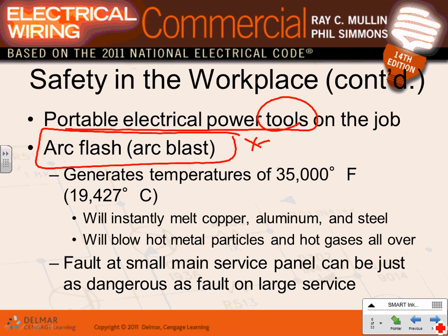If you are within 5 feet, your chances of having a first, second, or third degree burn are very high. Number two, your chance of being pushed against the other wall as a projectile is also very high, and your chances of losing your hearing because it's so loud are very high. The chances of losing your vision are also very high. So there are a lot of issues involved. Copper will expand, guys. This temperature will expand the copper and aluminum and make them bullets. When you have an arc flash condition inside the switchgear, it could create multiple bullets shooting at you. So there are a lot of issues involved in arc flash.